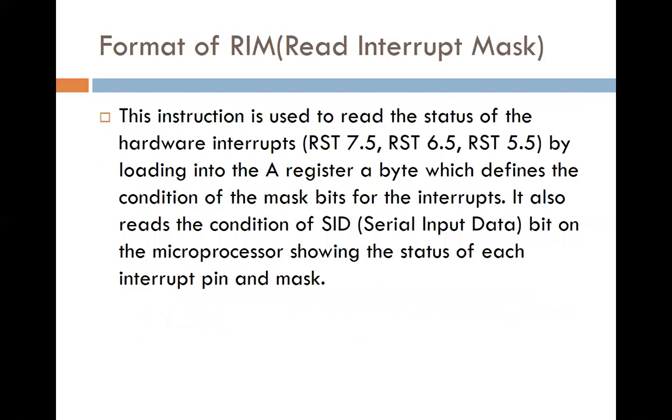Format of RIM, read interrupt mask. This instruction is used to read the status of the hardware interrupts RST 7.5, 6.5, RST 5.5 by loading it into the register A.